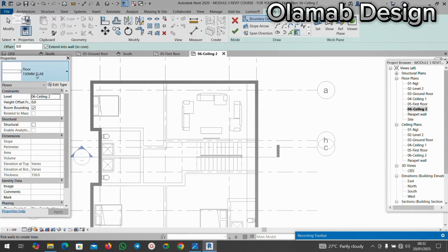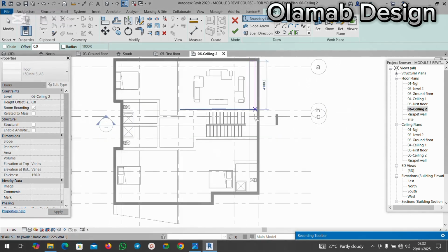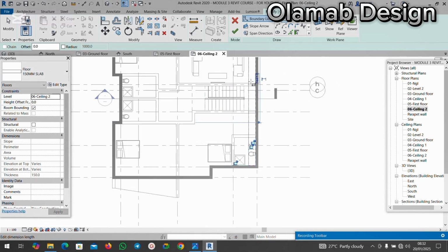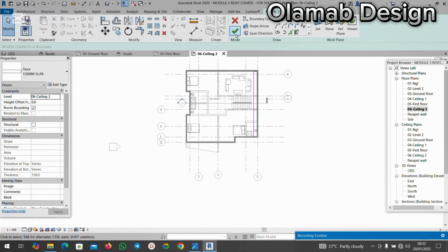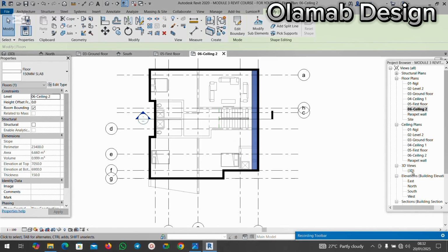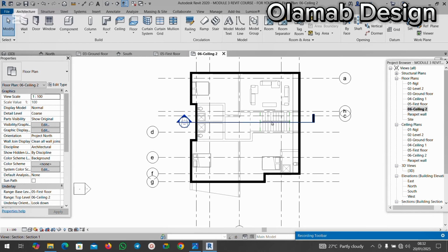So let's say I want to use this 150 floor slab. By now you should know how to set your floor materials. I'll go to rectangle and I'll draw that slab in the rectangle form to occupy that space, that 600 space where the roof is getting to. Okay, so let me finish it up now. Let me say no, I don't want it to attach. Then if you want to see this now, you have to have a section. Okay, that is when you can see it.